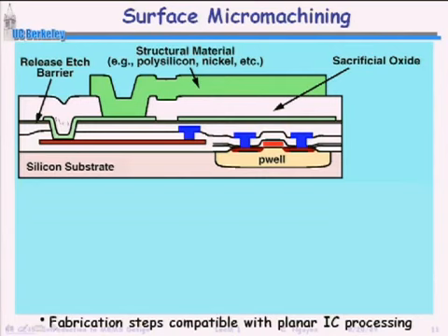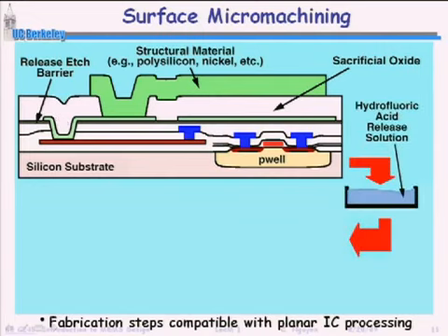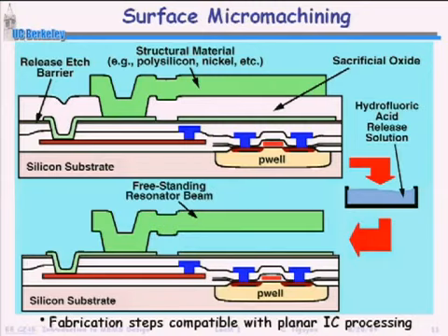This was a 3-mask process that we just went through here. Okay, very simple, but not so simple if you don't understand stress and strain. If you don't know what you're doing, you can do all these steps, and if you just went into an IC foundry and did all the steps, you would not end up with this. You would end up with something that looks like this, maybe anchored here, but this beam would be bending up like this, or might be bending down. Or maybe the beam is not even a contiguous beam, it's falling apart because it's just grains that are falling apart.